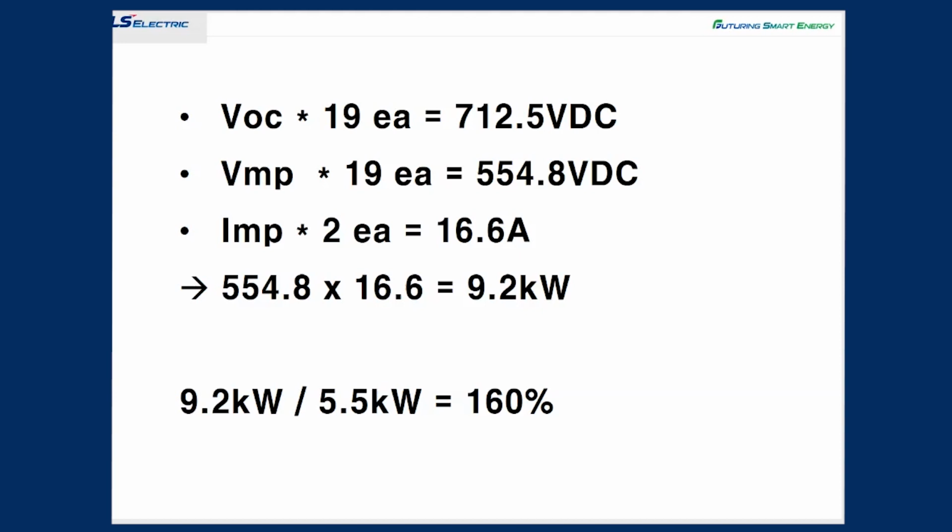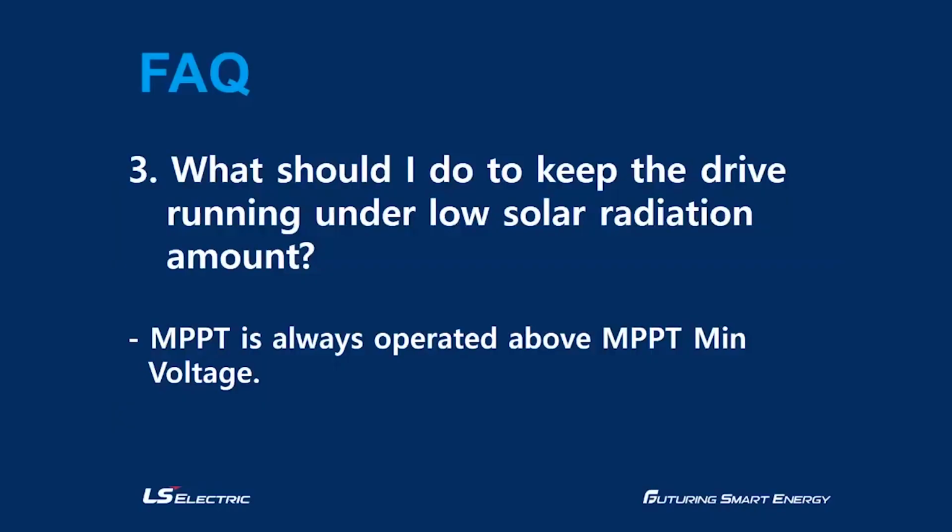I see. My third question. What should I do to keep the drive running under low solar radiation? MPPT min voltage is the minimum voltage that should be retained for MPPT operation. And MPPT is always operated above the MPPT min voltage.